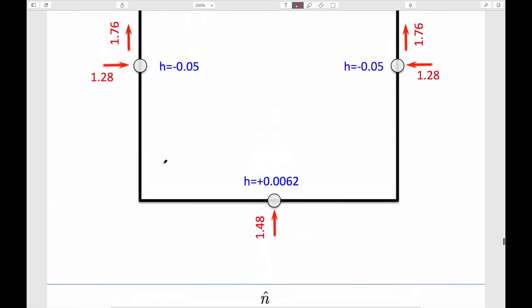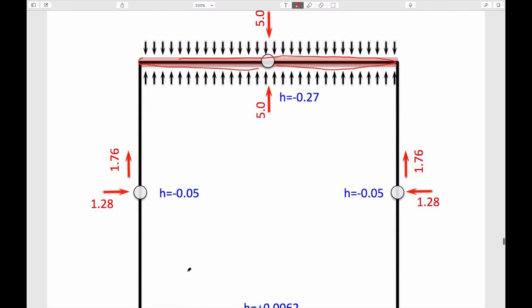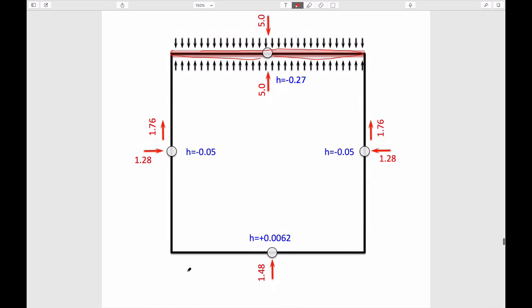So where is it? This is it. Yeah. So if you take the source, actually it's a sink, isn't it, in this particular case, because it's coming into it. So this is just showing that there's a flow into it. If you take this uniform source and apply it over this side, which is in an infinite medium, then we can calculate two things. We can calculate the head that's induced by this source at any point within the medium, and we can calculate the flow velocity that results from this. So just using those equations, this is what you end up with.